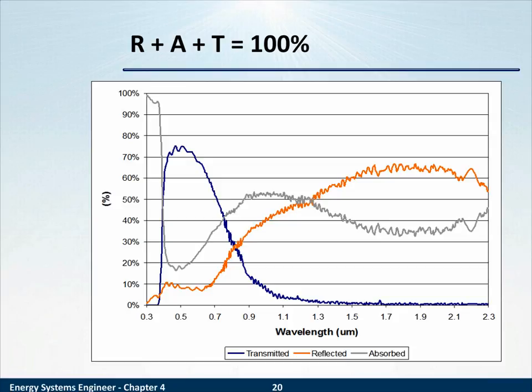And then as you get off to the right of 0.7 into the infrared, now you see the infrared reflection is very high. So what you can see from this graph is this is a film that has virtually no UV transmission. It blocks it all. It looks clear, and it blocks heat through reflection instead of absorption.